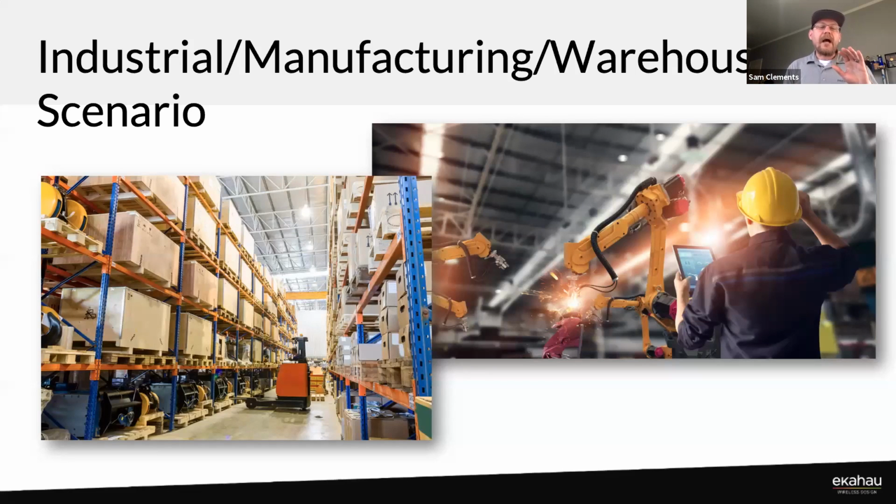And you can dive off for a week on the differences in doing a survey in a warehouse. Do you do high gain directionals? Do you do spotlight coverage? Do you do omnis? Do you do backfills? Do you do just a million and one different types of ways to do a design?